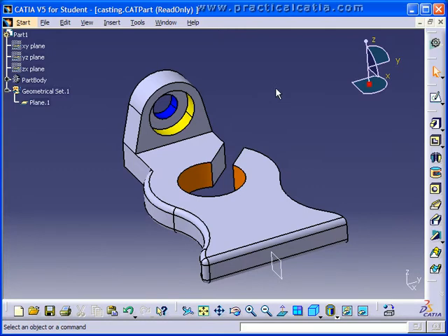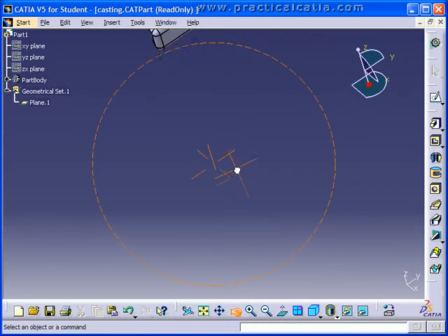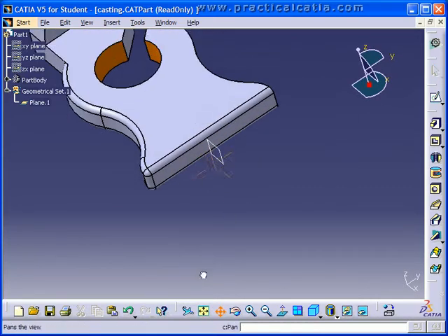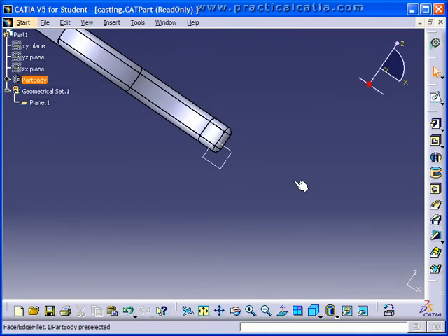The next tool we're going to discuss is the normal view tool, and it actually performs a couple of different functions. When we click on it and we select a planar face, it rotates the view around so that we're looking perpendicular to the planar face. Also, if we click on normal view and then select a line, it looks down the point view of that line. So go ahead and minimize the presentation and experiment with the normal view tool. When you're done, come on back to the presentation.